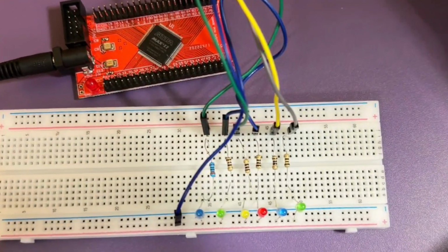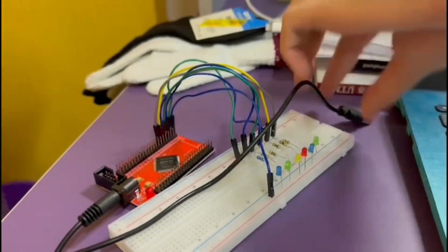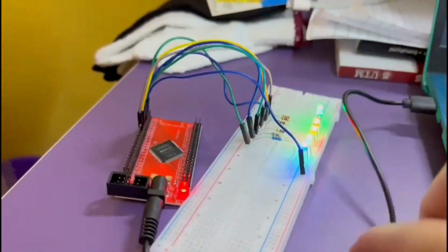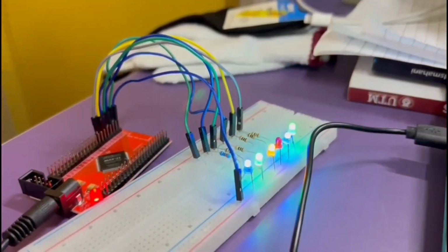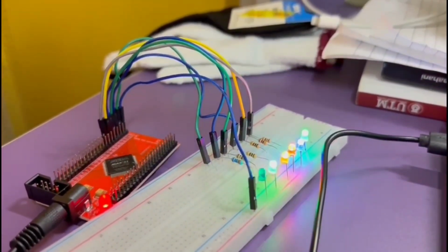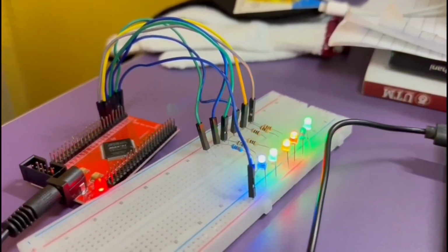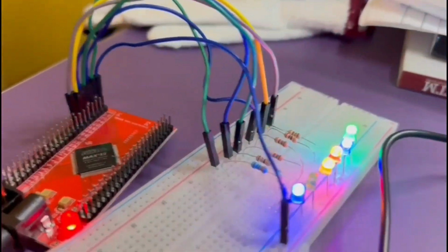Then all the assigned pins appear in our schematic. Next, we connect all the LEDs and resistors as shown in the manual, and now this is our connection. Then we program everything we did until now into our CPLD using the USB Blaster, and let's look at the result. Upon giving the power supply, the LED shows an interesting pattern. We can observe that one LED is turned off in order each second, constantly from right to left, and from left to right. So this is our milestone 2. Thanks for watching.